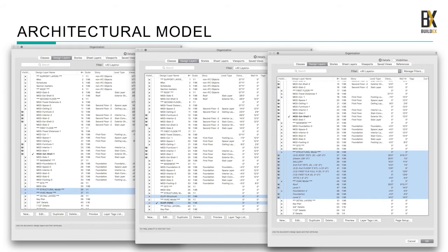And as I create the referencing of my shuttle files, I can add, and you can see on the last one, all of my structural layers and my mechanical layers, and I can group them correctly under that banner that I preset in my template.